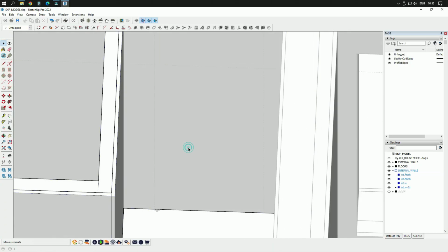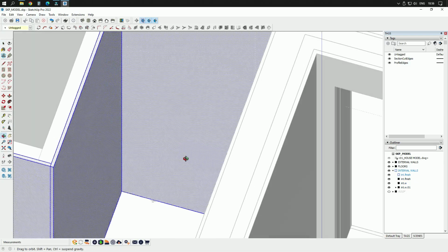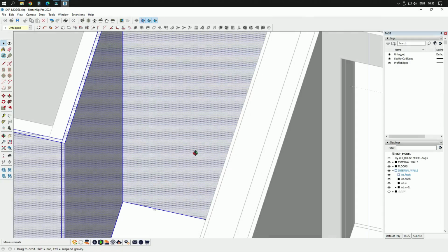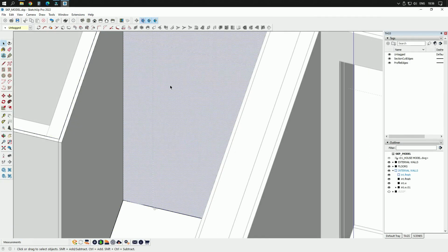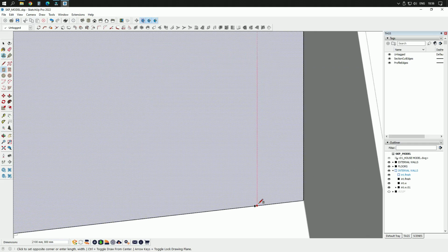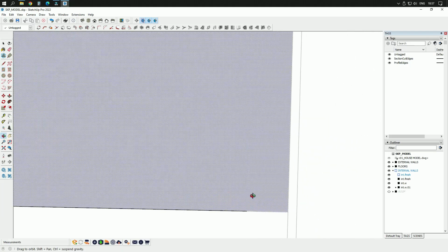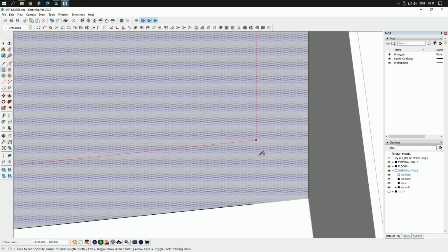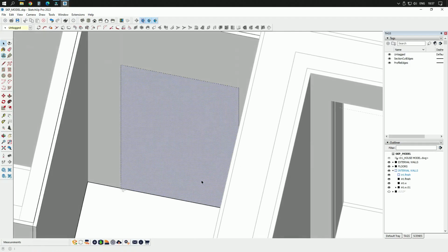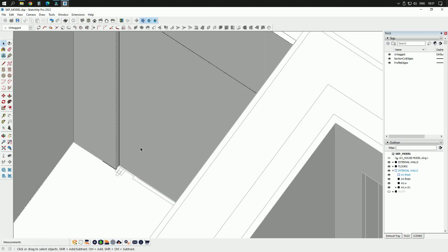This time I will show you another way to create doors. You have to go into the group, select this wall, and then by drawing a simple rectangle you can pick all these points here. You have to see where your reference line is, it's here. And now using Push/Pull, I will press P on my keyboard and extend this face up to the final point of my layer.